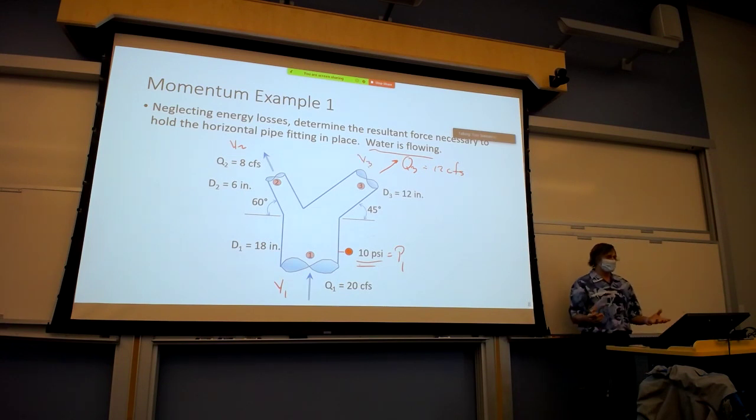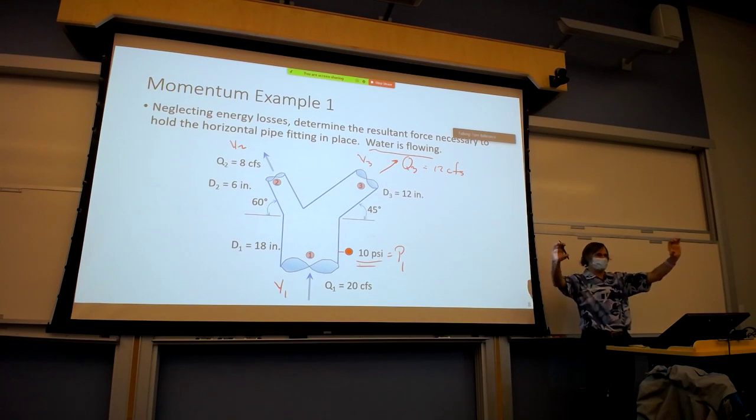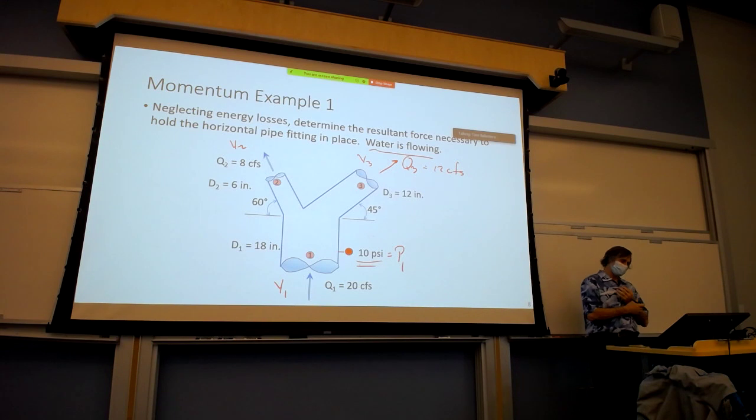And the question is, do you see a dramatic change in the geometry of the flow field at a short distance? Yes. It goes from a single jet to two separate jets. And then also, is there a change in the velocity vector? Well, yes. First, the direction changes. You do not need a change in magnitude for there to be a change in the velocity vector. It could just be direction.